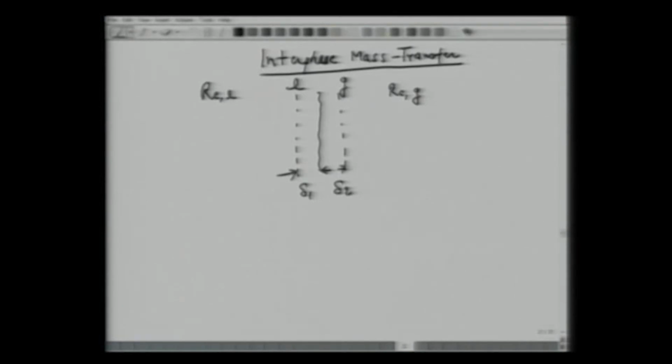So two diffusion resistances. Suppose this is your sulfur dioxide and on this side we have water, and the sulfur dioxide diffuses across this interface. In interface mass transfer, again we will have bulk concentrations. This concept of bulk concentration was defined earlier. We have Cb, or we can say the diffusing species is A in the gas phase.